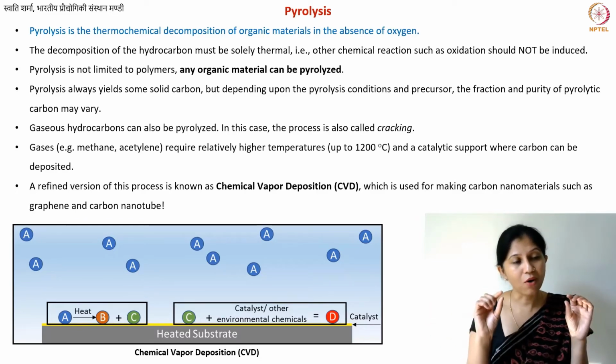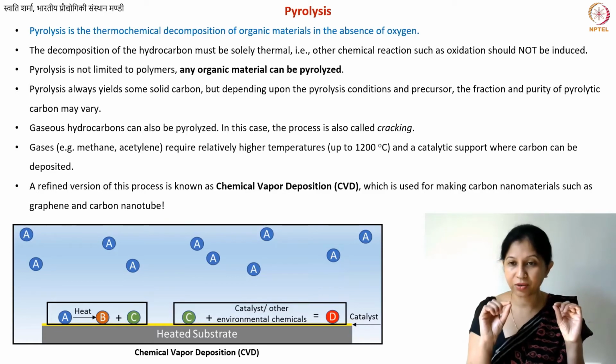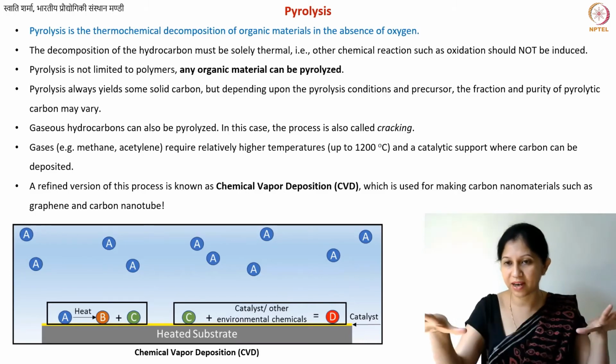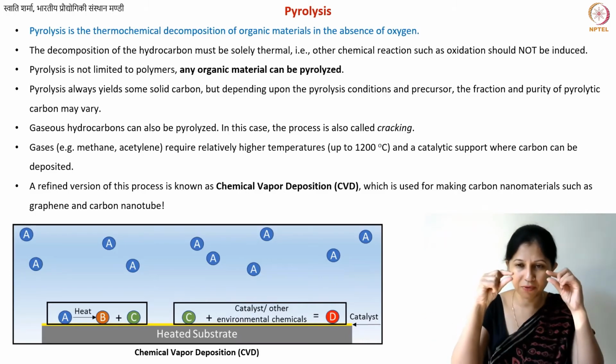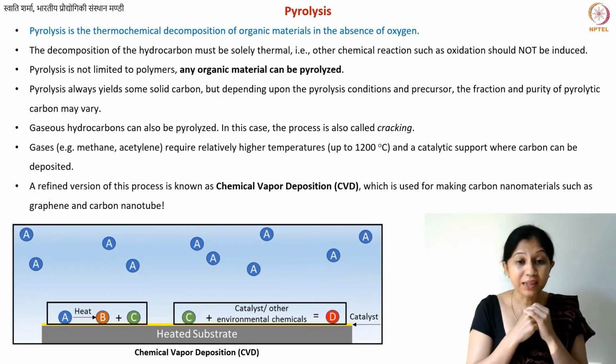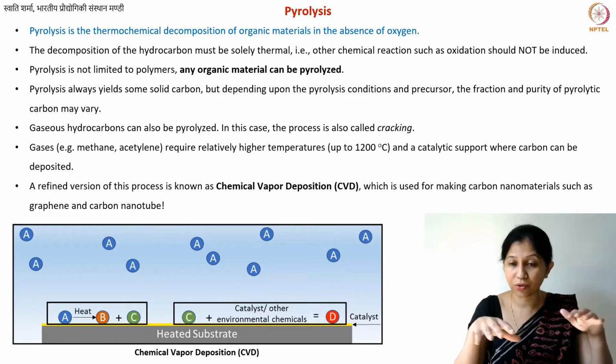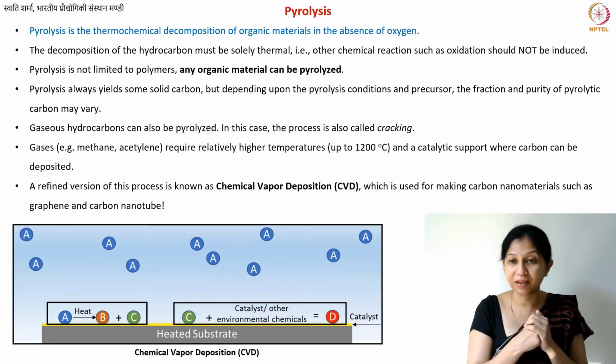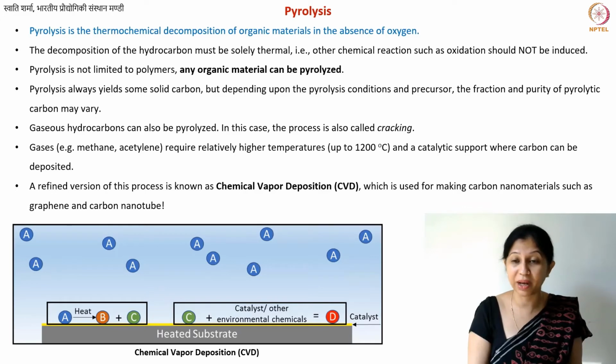However, if you control the CVD parameters to some extent, you can get, if not single, maybe bi-layer graphene. It's like 2 layers of this entire material, because you want to make the film as thin as possible. But in that case, you may also get more defects, because you have this dendritic growth, or the film growth, right? In some cases, the film is not properly grown, or it still has a lot of defects, and you stop the process. So you can get thinner layers, but then the quality of the graphene may not be so good. But this is a process actually commercially used for making the graphene flakes.